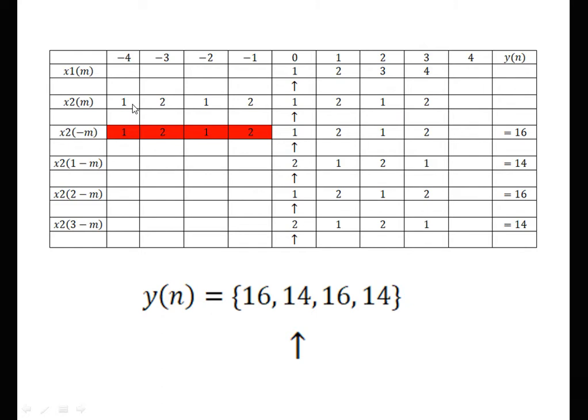Here on the right hand side, and on the left hand side also, we can write down 1, 2, 1, 2, again 1, 2, 1, 2, and next again 1, 2, 1, 2. This means the signal is periodic in nature. Therefore we require to write down these values because they are not 0, as the signal is periodic in nature. Now first signal x1 of m, next input is x2 of m. Our first signal remains constant, so we are just continuously multiplying with these values.